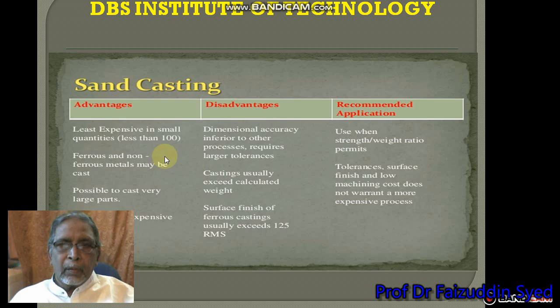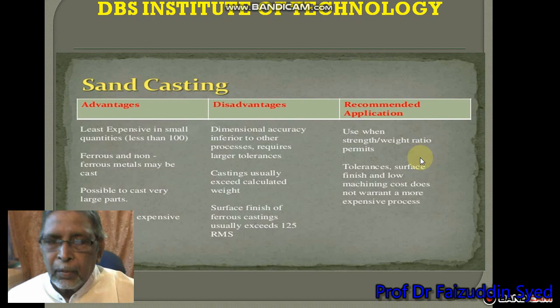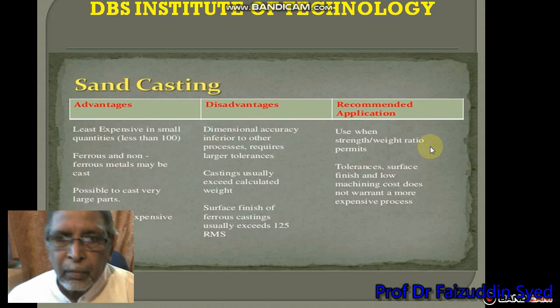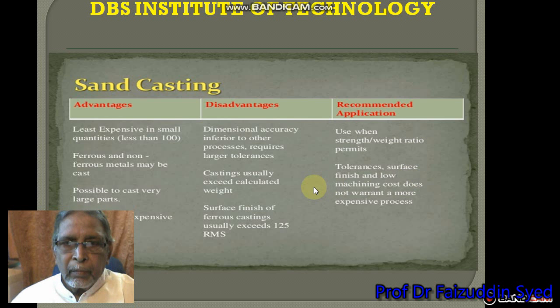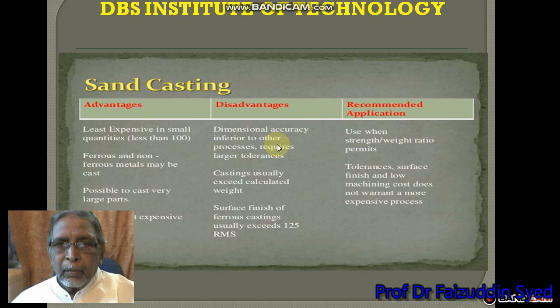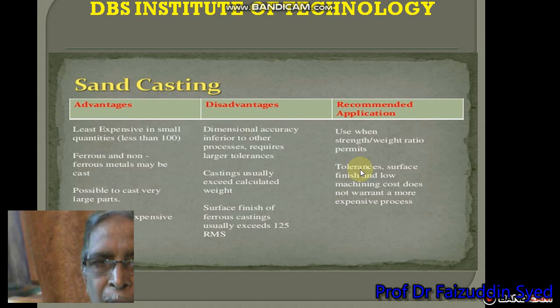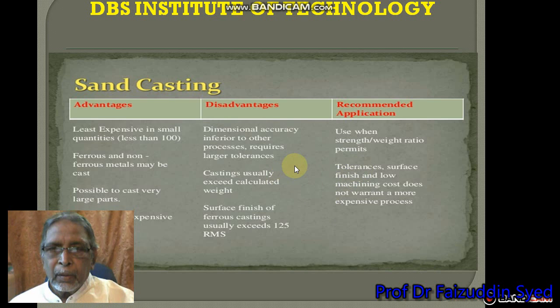Now we can see the advantages and disadvantages of sand castings. The advantages are that this is least expensive in small quantities. Ferrous and non-ferrous metals may be cast. It is possible to cast very large parts. It has the least expensive tooling.